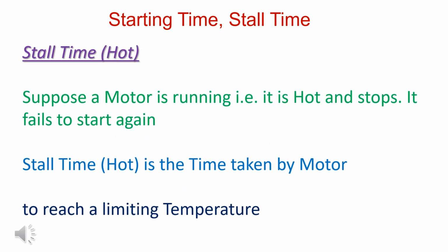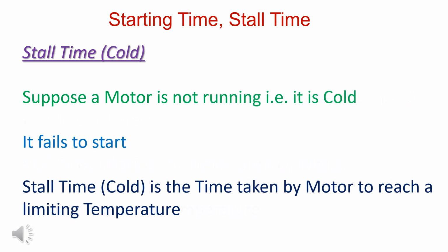Suppose a motor is running and stops. It fails to start again. Safe start time hot is the time taken to reach limiting temperature. Suppose motor is not running and it fails to start. Start time cold is the time taken by motor to reach a limiting temperature.